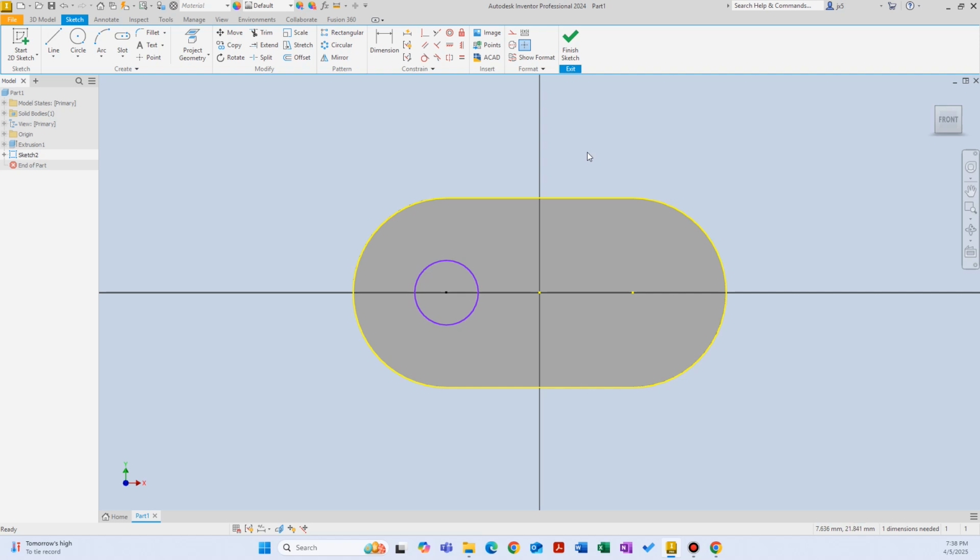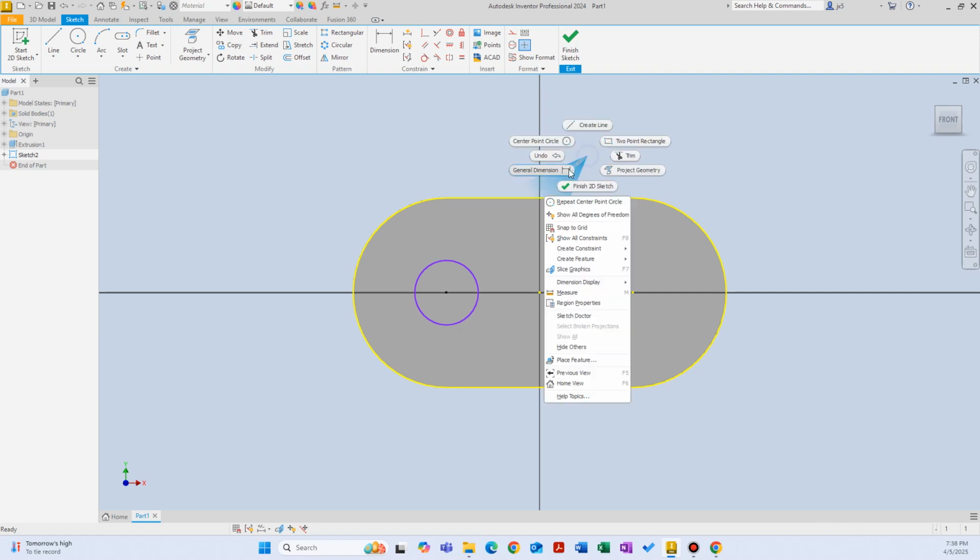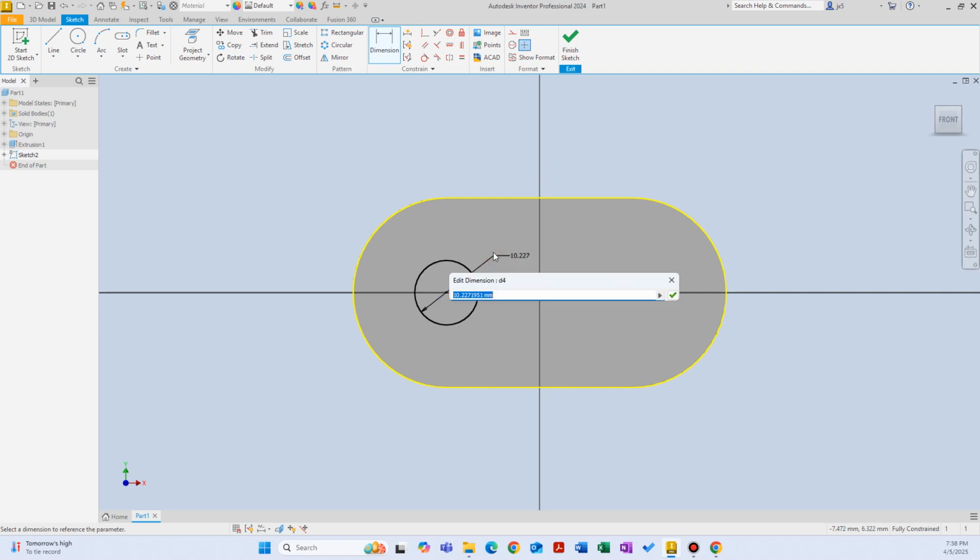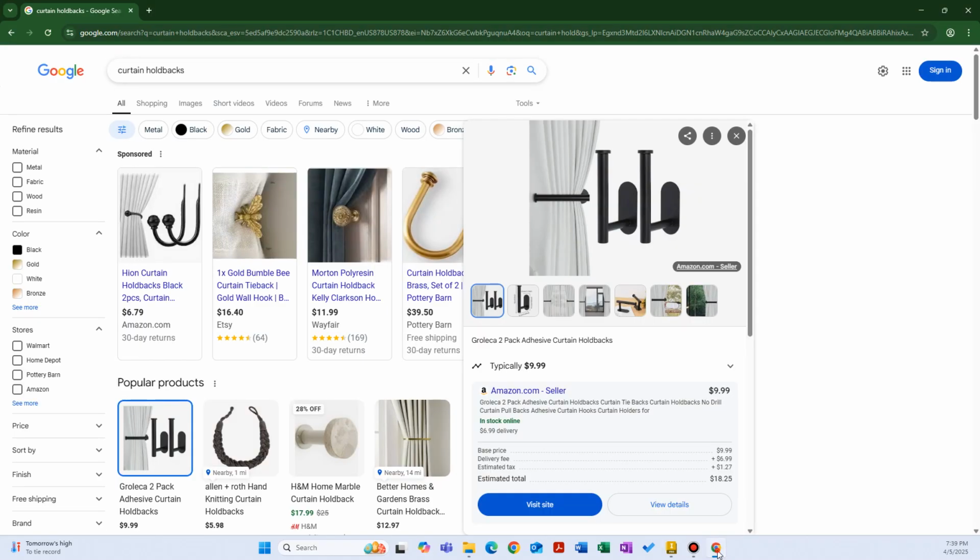Maybe I can just drill through it so it doesn't have to be that accurate, but let's make that maybe 5 millimeters. Yeah, so 5 millimeters should be enough for a screw to go through and also hold the base. I mean, worst case scenario, I can use a washer, but oh, hang on, we were not doing the screw hole, so this is actually the second section. Sorry about that. Let's make that 10 millimeters so it's a little bit more beefy.